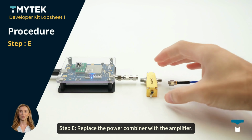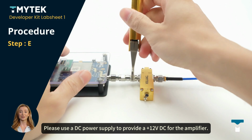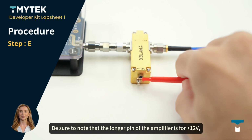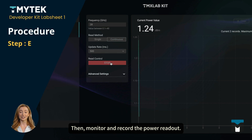Step E. Replace the power combiner with the amplifier. Please use a DC power supply to provide a plus 12 volts DC for the amplifier. Be sure to note that the longer pin of the amplifier is for plus 12 volts, and the shorter pin is for GND. Then, monitor and record the power readout.